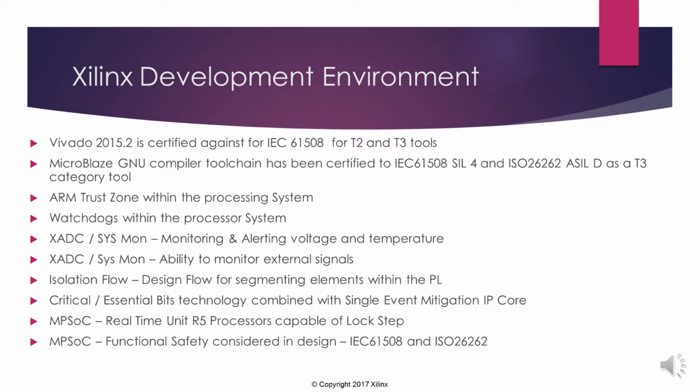But you know, within the processor system, we have the ARM TrustZone, which allows us to create orthogonal worlds within software, such that we can have different levels of software running and they can see different elements of the hardware, such that we can have a much more safe and controlled and secure system. We have watchdogs within the processing system if we're using a Zynq, to ensure that if we lock up, we can come back okay. We have the XADC and Sysmons, as I mentioned earlier.